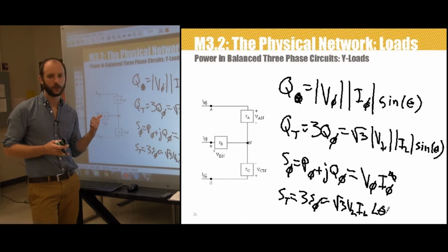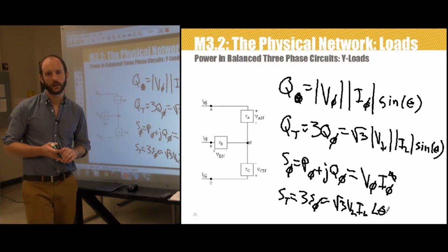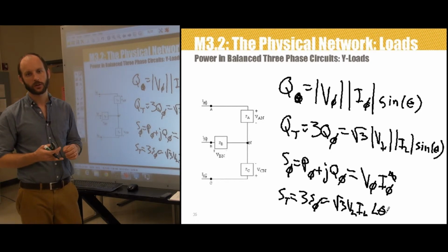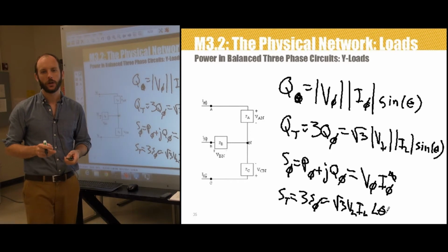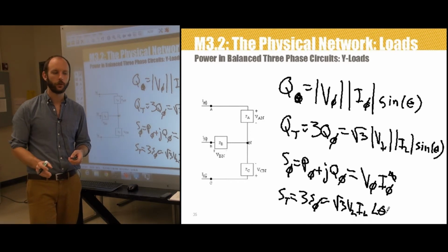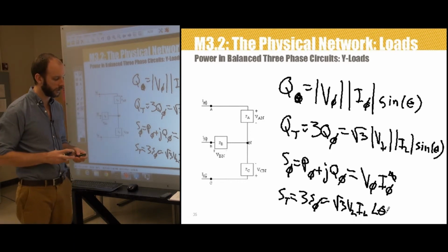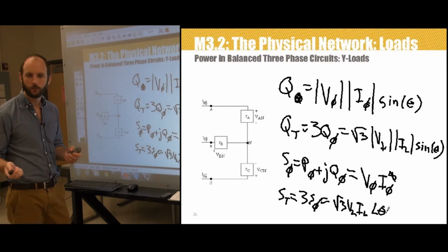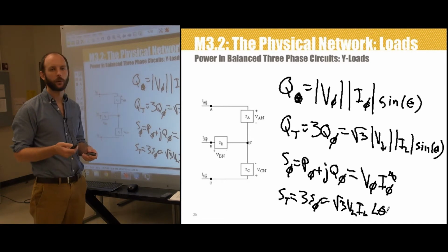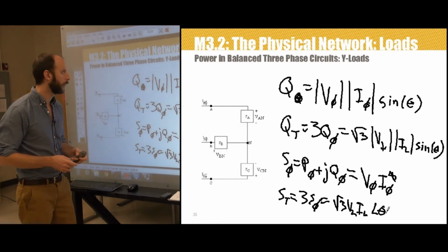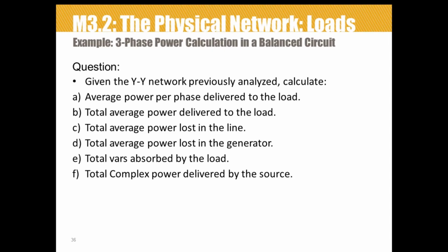Before finishing with an example, I'm going to note that in power systems, when statements are delivered regarding power delivered to a three-phase load, the figure quoted is almost exclusively total power, unless for some reason they indicate otherwise. So now we'll do an example of power in balanced three-phase loads.